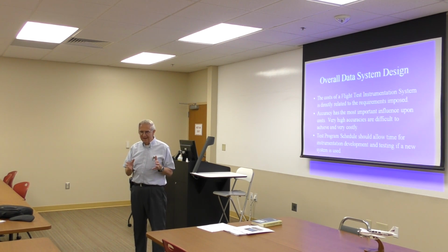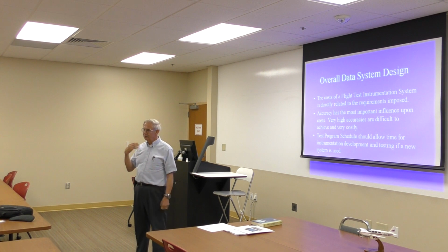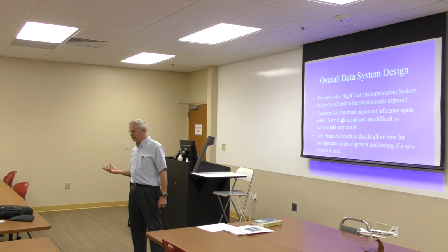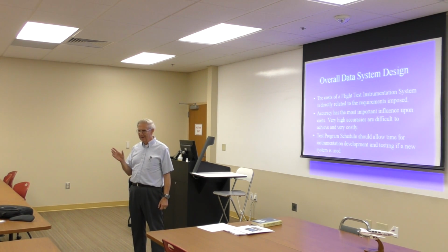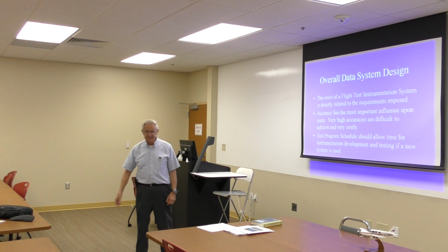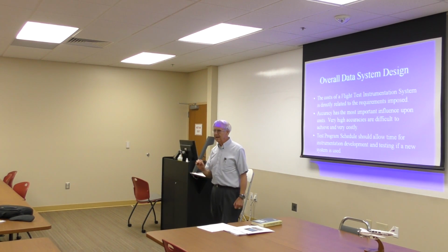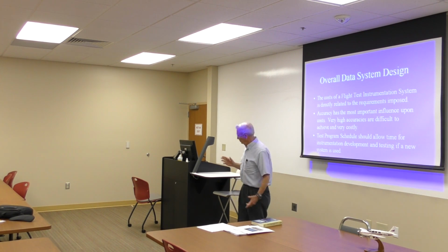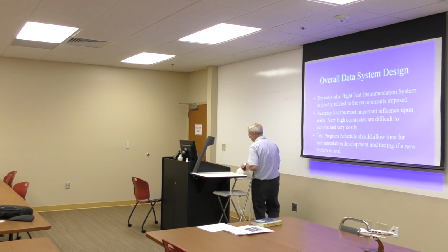Don't get fooled by that sort of thing. Let me tell you, when you start wanting accuracies of 0.25%, that gets real expensive. And if you're recording it on a system that at best is 5%, why did you spend the money on that 0.25% system? But let me tell you, you see that in this business with regularity. So, watch out.